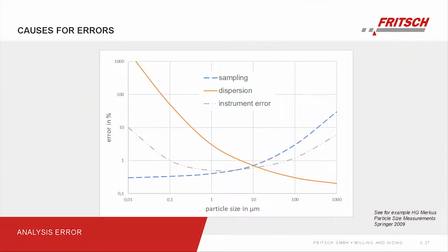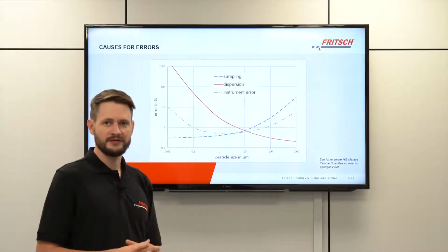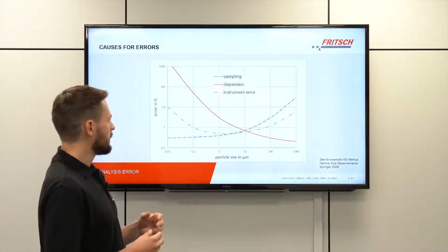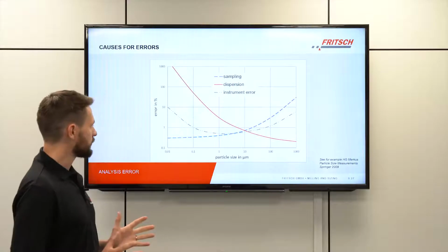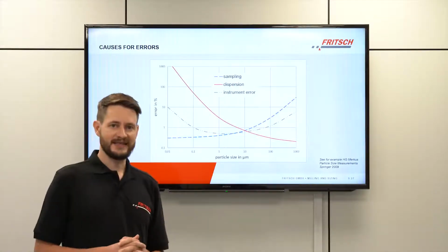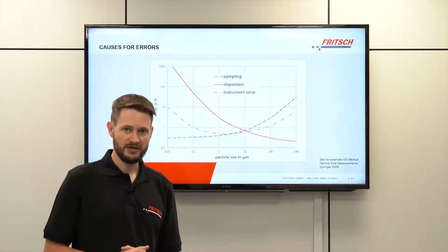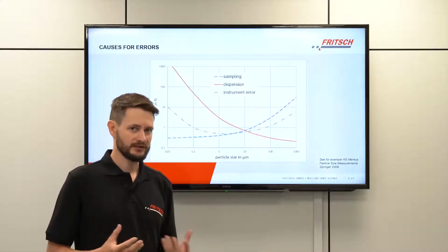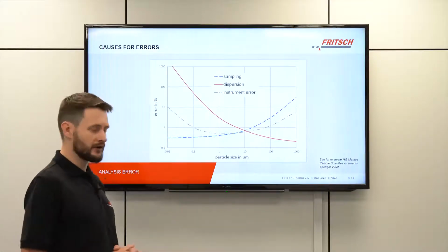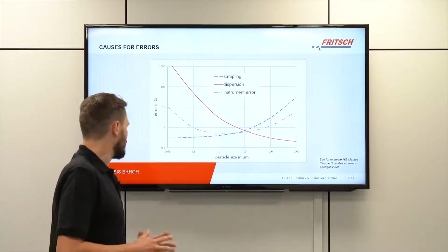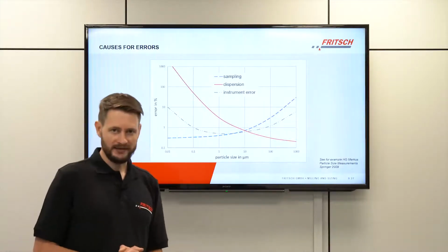Now you would get, of course, different particle sizes settling down in different locations of your sample container, wherever you keep them. If we just take a sample by chance from one locality of this sample container, there would maybe be some particle sizes overrepresented. Here it's very important to do some kind of sample dividing before making a measurement in order to have all different particle sizes represented in your sample. And this error, as you can see, becomes way less critical if we reach small particle sizes.